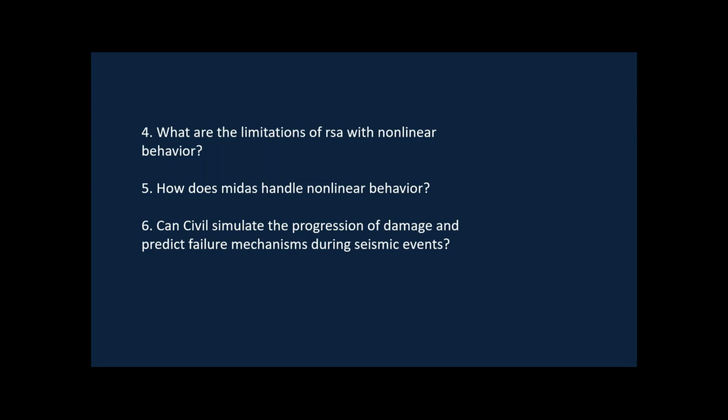We have the nonlinear analysis tab, wherein you can specify both, in terms of plastic hinges or hysteretic loops, depending upon the type of analysis. If you're doing a pushover, plastic hinges can be assigned. If you're doing a nonlinear time history analysis, different hysteretic models are available in the program by which the nonlinear behavior can be captured.